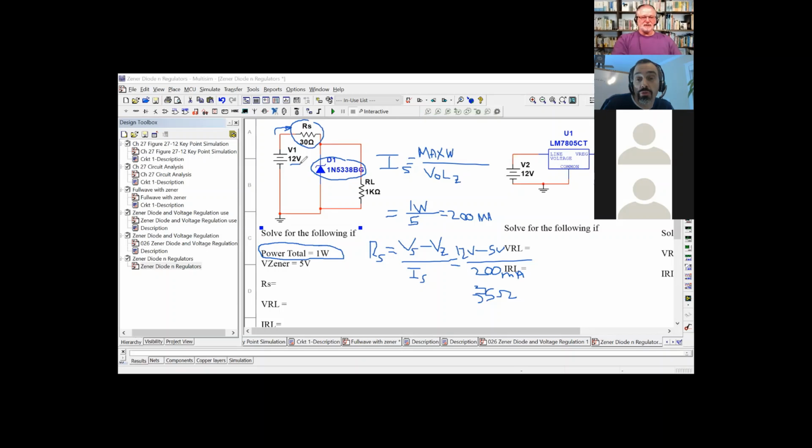How much would be flowing through? 12 volts. 12 volts, right. So where did the 5 volts come from? That's the 5 volt rating of the Zener diodes. That's the rating of it. So Zener diodes have a voltage rating, and they're regulators. That's what a Zener diode is.